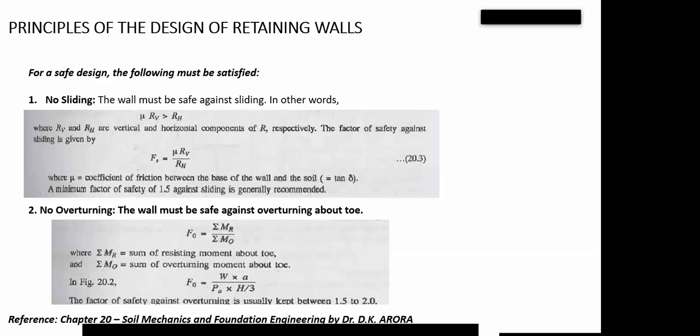Now, although if you have your surcharge load, don't forget that your surcharge load too will also have its own what? Its own lateral pressure. It's also horizontal. In that particular case now, you are going to be having your active earth pressure from the soil itself, and you're going to be having the active lateral pressure from the surcharge, because the surcharge load will also cause a horizontal pressure, like we explained earlier, which was rectangular in section.